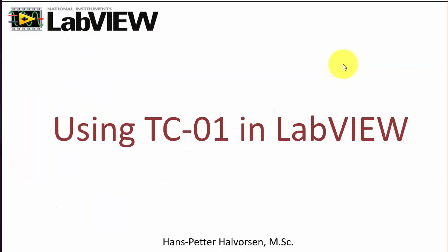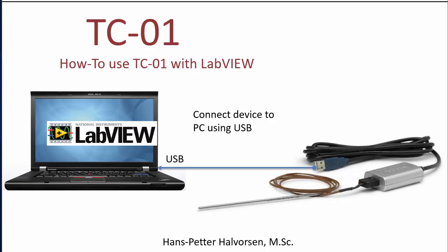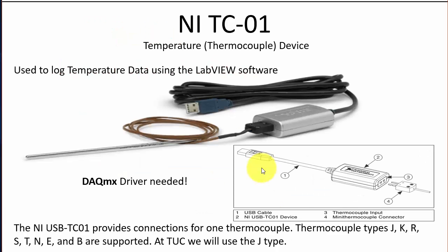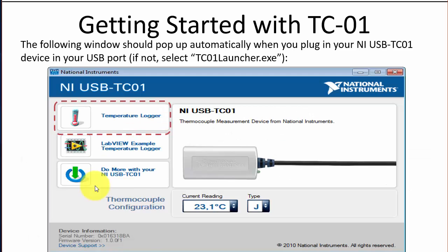So, how can we use this device, TC01, in LabVIEW? First, we need to connect the device to the computer using the USB cable. Also note, we need to have this DAQmx driver.